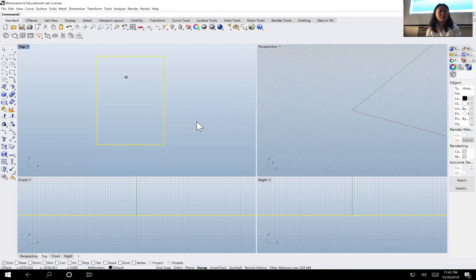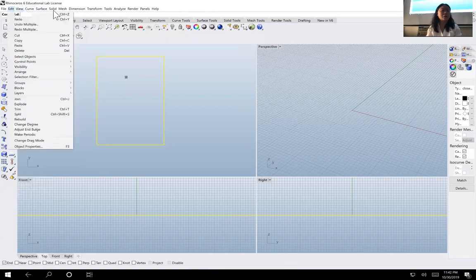Once this is done, I'm going to build the thickness of the wall. So I would use something called offset. The wall is 240 millimeters in thickness. Sometimes that's how we work with the computer. If you remember where the toolbars are, this is the pull down menu.